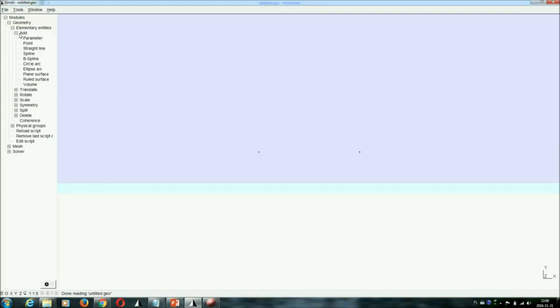That is probably clear, but when you want to create geometry, you first need to create points, then after creating points you go to creating lines. And finally you go to creation of surfaces, which is enough in 2D, but if you want to go to 3D, you then go to creating volumes.